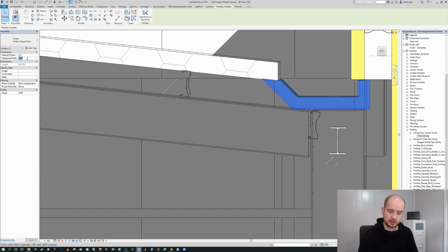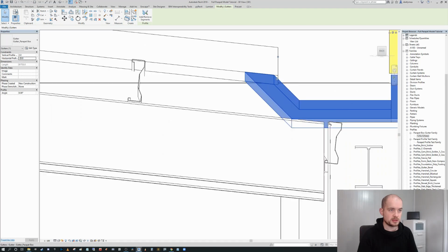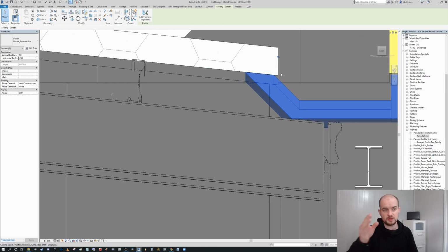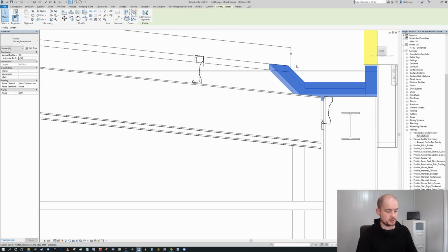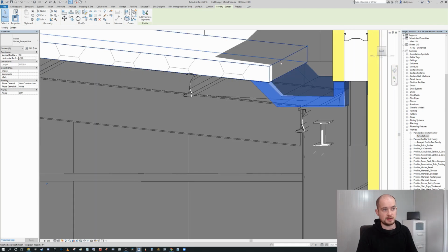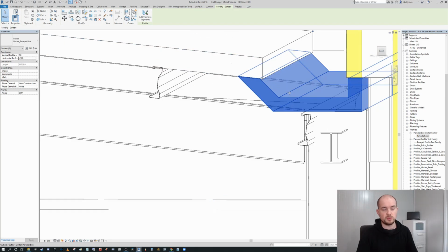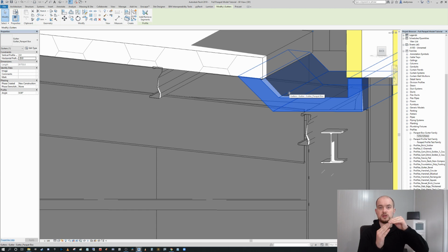I'm actually going to change that to -20. Okay, and what I wanted was a slight lap between our roof construction and our gutter. Our gutter shouldn't emerge from the joint. There should be a slight lap. So if you imagine that you'd have some sort of flashing profile coming down or some sort of corrugation on the roof coming down and out, you'd have a drip, and you don't want that drip to be right at the join of the gutter. You want the gutter to be offset back, okay?